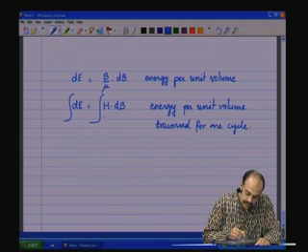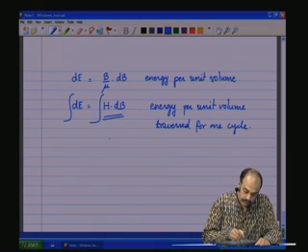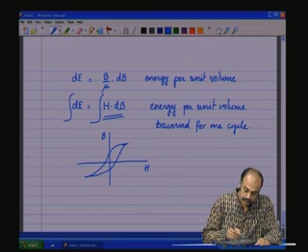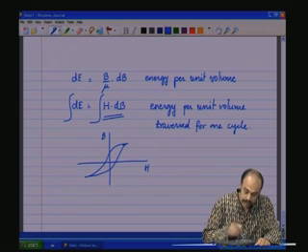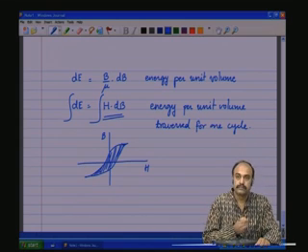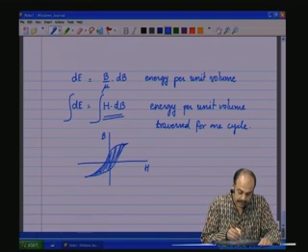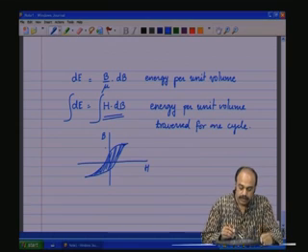Now, what is this? From the BH loop, we have this. As B is traversing positive and negative, H is also traversing along this, and the integral of this is going to be basically this area, and that area is going to be lost forever. That energy is not going to be got back.